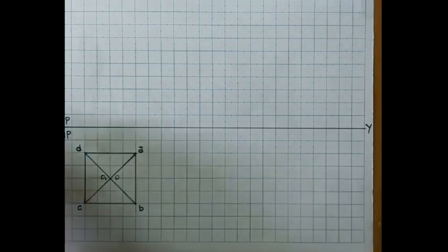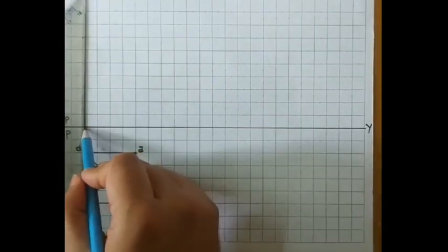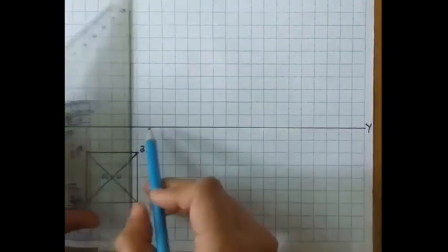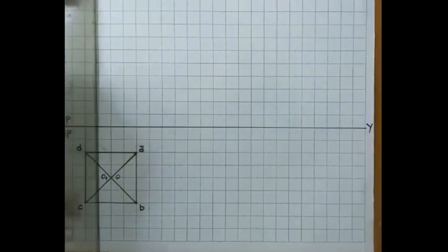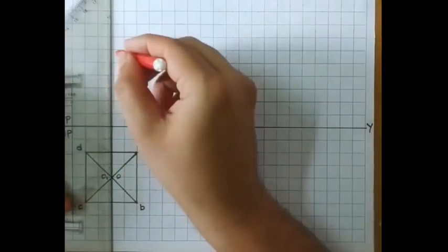Now to get the front view, I am going to project all these points to the front view, that is to VP, and these projection lines should be chain thin lines. The height of the given pyramid is 60 millimeters. I am going to draw the axis for 60 millimeters.